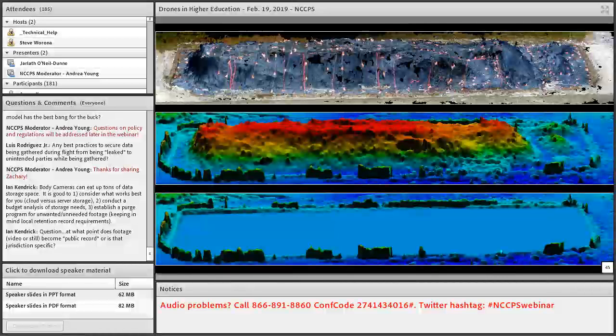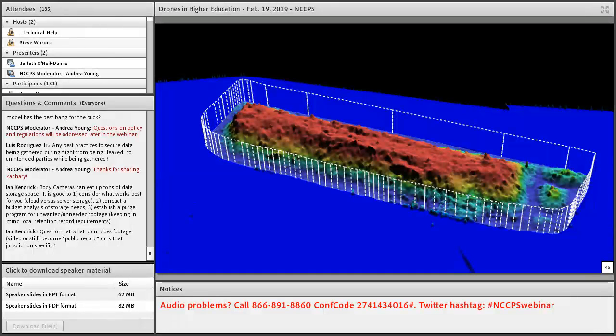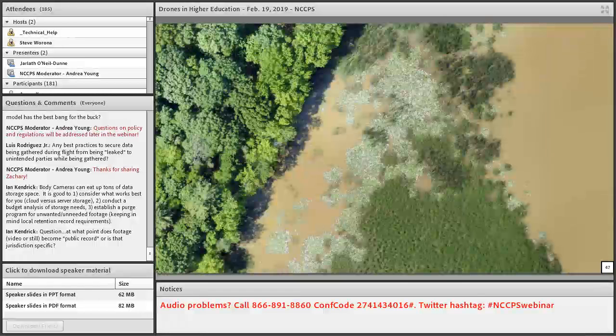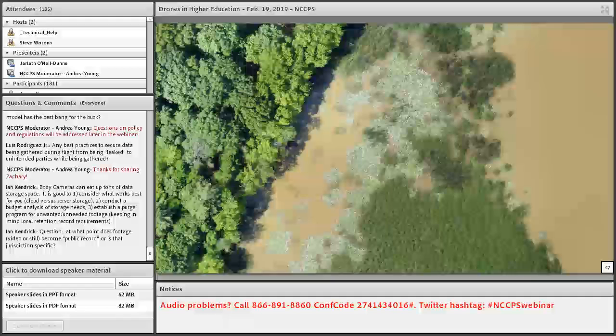And so with a 7-minute drone flight and 30 minutes of computer processing time, we built these 3D models that were able to give them an accurate representation of how much soil they had to get out to a landfill that could handle contamination. And so you can imagine if you're doing construction on your campus and you need to do verification, perhaps a contractor has billed you for a certain amount of fill, an easy way to get out there and verify that is to use drone technology. You'll find that in your departments of natural resources, or your agricultural departments, that drone technology will be gaining interest.